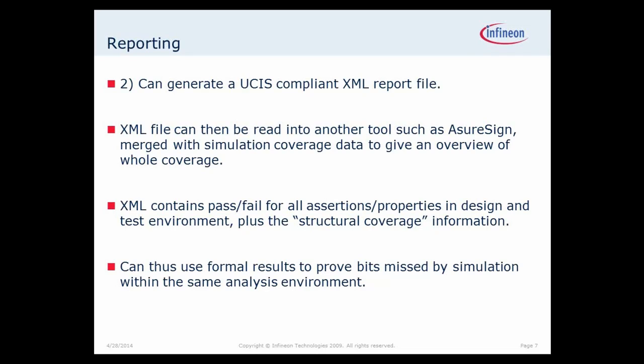Thus, if you've got holes in your structural coverage from your simulation, you can use your formal results here for closing those holes without necessarily needing to work hard on your random test bench.